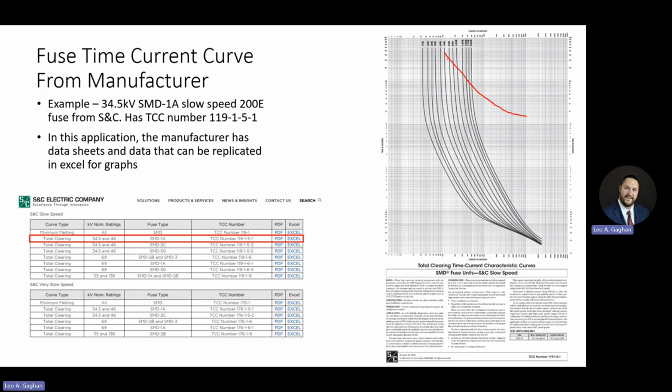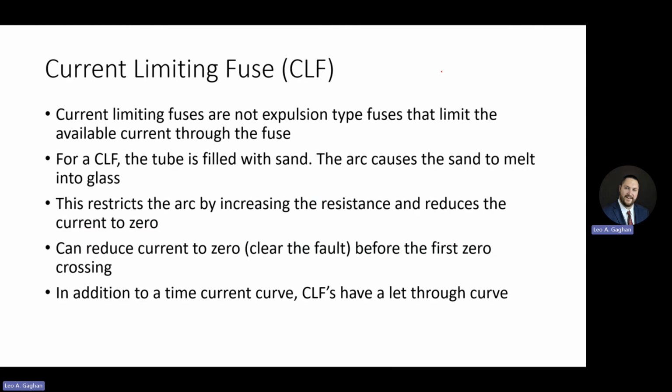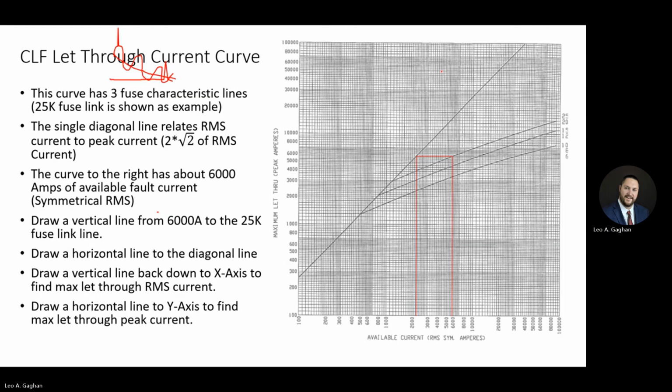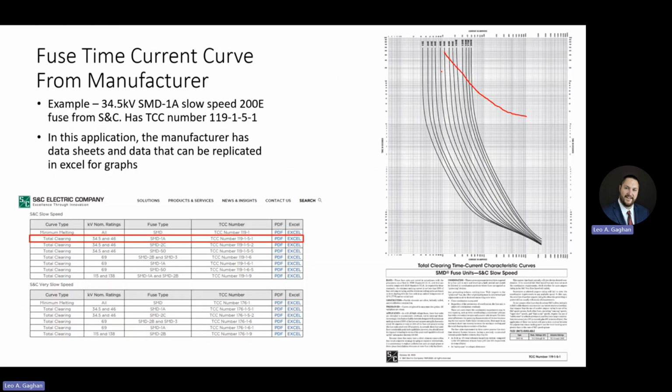We would still have this characteristic over here for high impedance ground faults that maybe the fuse can't detect. But that intersection point is, depending on what utility you're working for, maybe something they're willing to accept. And again, you have that intersection because the ground element is more sensitive than the fuse. If it's more sensitive at one point or another, you're going to have an intersection. It can't be avoided.